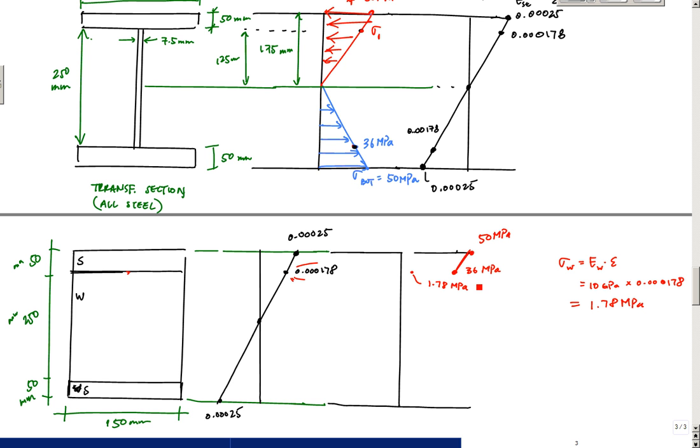And so my stress profile here in compression, I would have here like this, and then I have this arrow right here, and then I continue with the step. There's a neutral axis right here, and here my stress profile goes down from here back to 0, like that. And so this is my compressive stress profile all the way down to 0 right here. And then the magnitudes of the values are the same in tension.